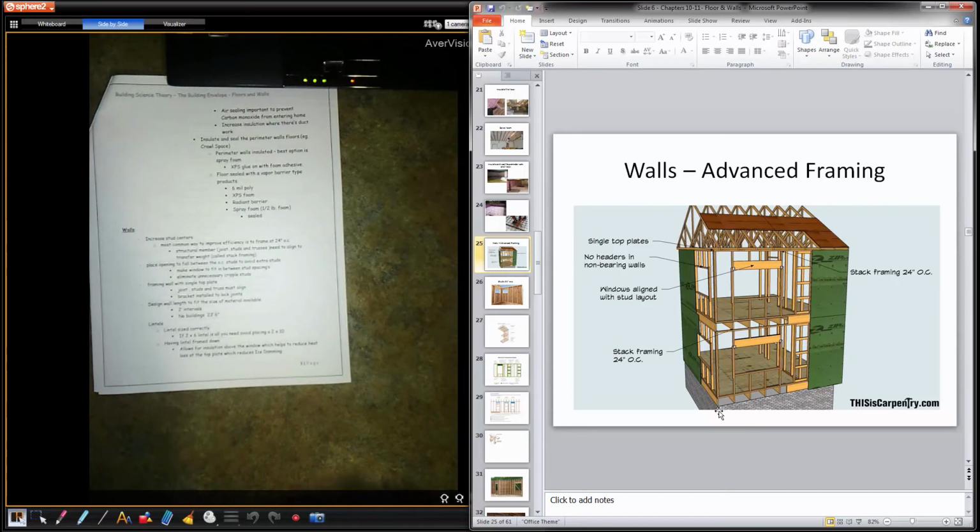Like, it's easy for us to see all these pieces aligning right now because they removed all the material. But during construction, you got to pay attention to that. You should be able to see a row of nails on the plywood to know where the joists are. Make sure your studs line up with that. Otherwise, it's not allowed. You can see here they went with a single plate. So a single plate, so it becomes even more important to make sure everything's aligned.